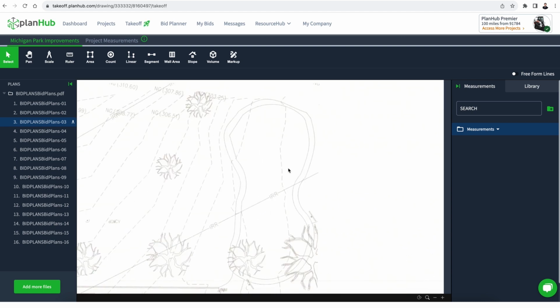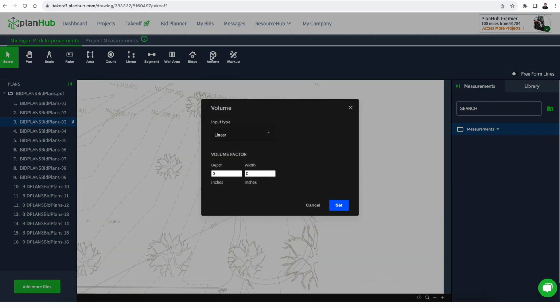where I'm going to create basically my takeoffs for 4 different depths: 48 inch, 36 inch, 24 inch, 12 inch depths. And I'm going to start with the deepest part first. One of the first things I'll do is make sure that this freeform line is clicked, it's gray, so that I can draw lines without having to worry about the line snapping to 0 degrees, 22 degrees, and 45 degrees. That really helps you when you're on a plan and you're doing true vertical and true horizontal. But in this case, I want to draw these lines as free as possible.